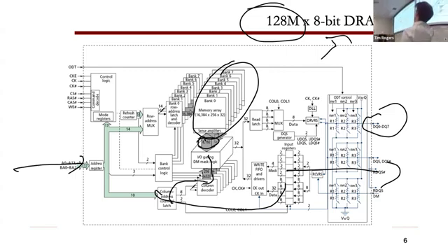So if I want a bigger interface, like let's say I want to read out 32 bits every time, I can put 4 chips together and call that a rank, okay? I'm going to control them with all the same control signals. I'm going to have different pieces of the data in each one. But logically, they're all going to go to the same address within a particular chip. And so that is a rank, where I fuse them together.